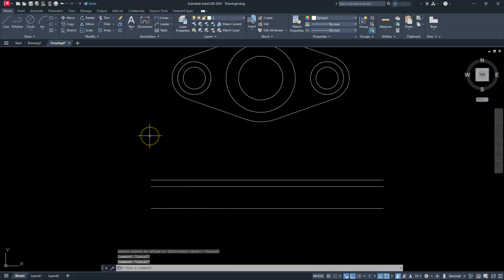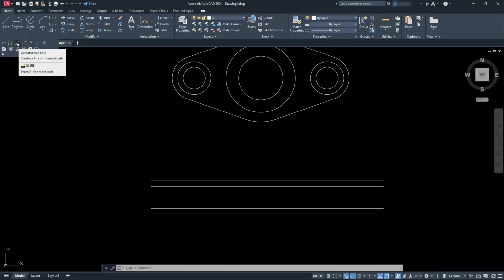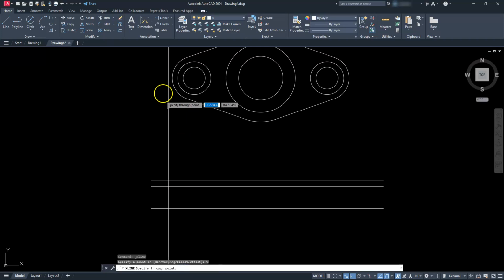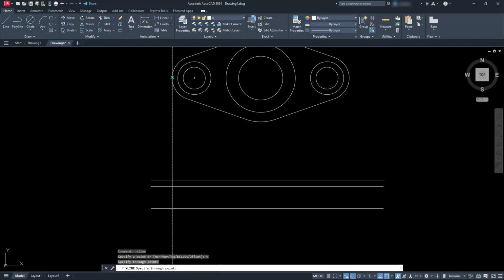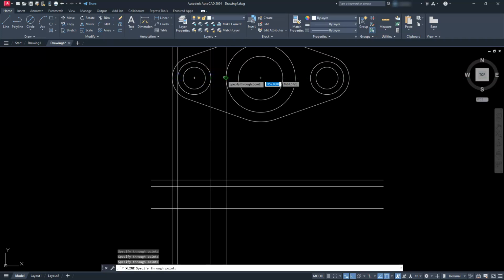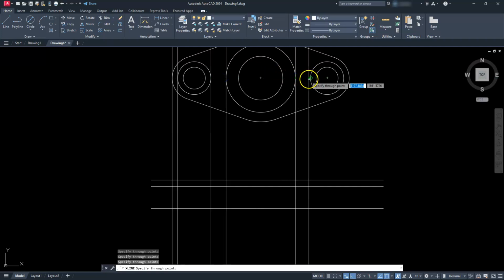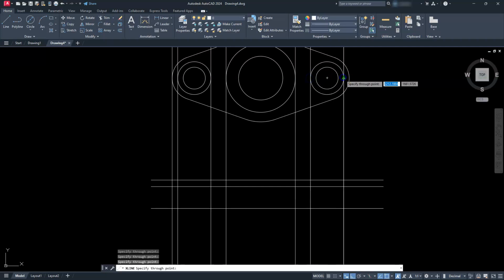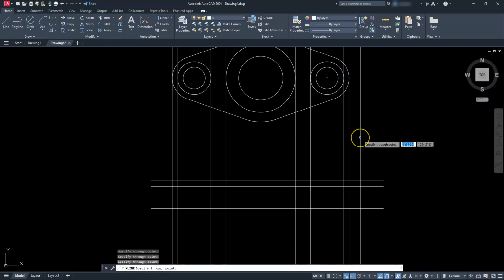And now, depending on what you want to work with, this is the next area. If you can see both of these, you can put a lot of lines on here. Otherwise, you can just keep it simple. But I think I'm only going to use a few lines, so I'm going to use the construction line command. I'll select vertical. And what I'm going to select is this midpoint, this quadrant, going to the outside of this quadrant. Keep working here and here. And I'll work on these two quadrants. So I'm here, here, and then finally this midpoint on the outside.